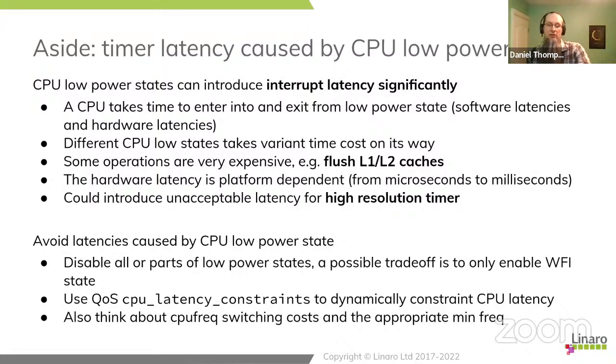On ARM systems, an interesting starting point is to say, we'll turn off everything except WFI. And if you're industrial, that's a very easy thing to think about. WFI does clock gating, but doesn't really get involved in power on or off, although it is defined by the microarchitecture. So different cores can implement WFI in different ways.